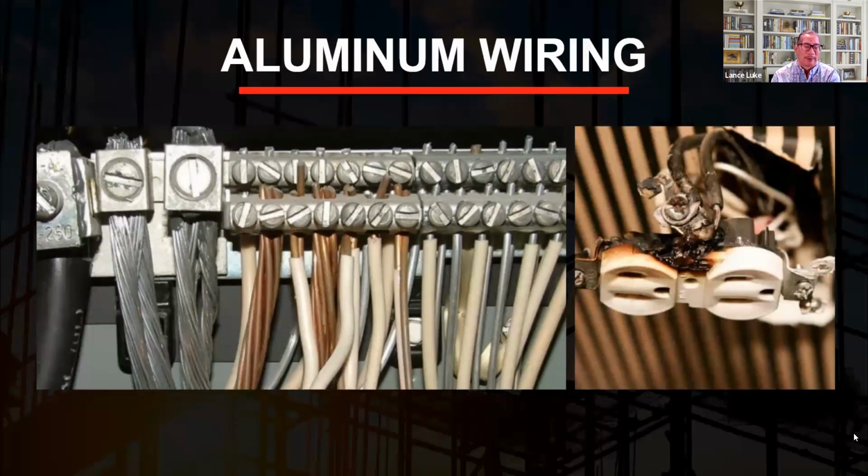So similar to siding, houses in Mililani and Hawaii Kai and Hawaii, I've seen a lot of aluminum wiring, not only in single family houses, but in townhouses as well. So it's not safe in my mind. So if your house has aluminum wiring, you may want to have an electrician check all the connections. And when I say connections, that means when the wire is cut, it's terminated at something. It's terminated at an outlet, it's terminating at a light fixture, it's terminating in a light switch, see? So anytime that wire is cut and connected to something, that's where you need to check.